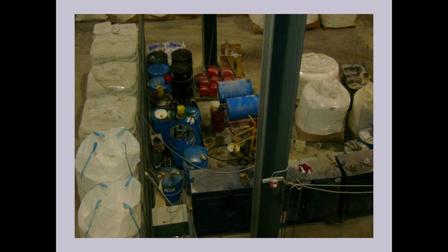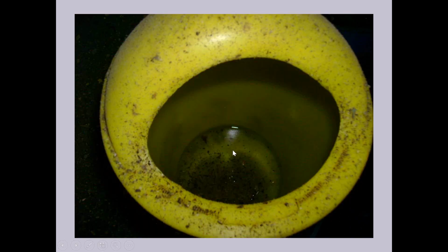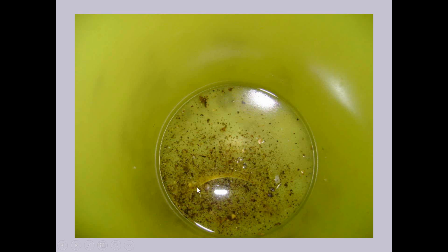Here's a lube storage area, and I took this picture at a facility. Look at the lube storage area. It's in an area where they've got silica and filter aid. There's filter aid and particles all over the lube drums and all over the lube equipment. Very bad lube practices. Here's one of the containers sitting down there. It was an oil container that they used to put oil in gearboxes. Look at the particles in the bottom of this container. The container on the outside is clean, but look at all these metal particles and dirt that was in the bottom of that container. And these things were getting dumped into the gearbox and equipment at this plant. So by changing these practices, we improve the life of the equipment.